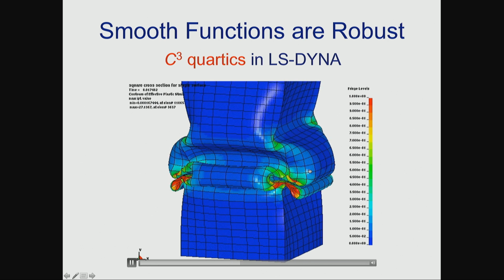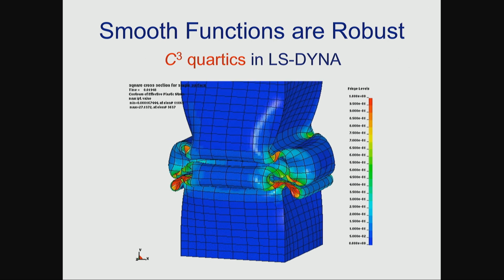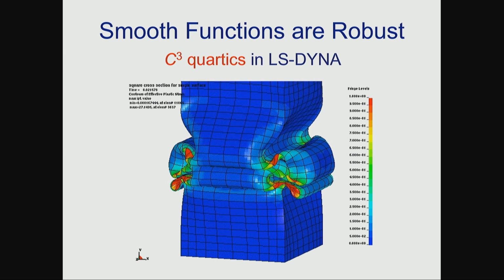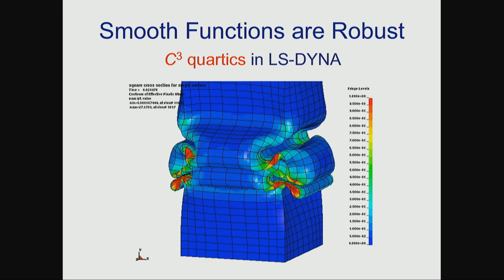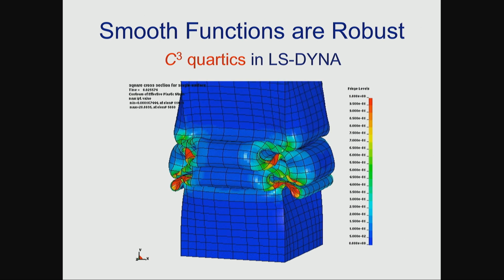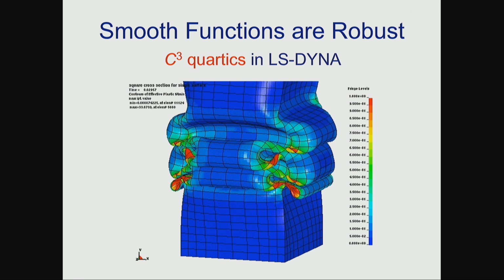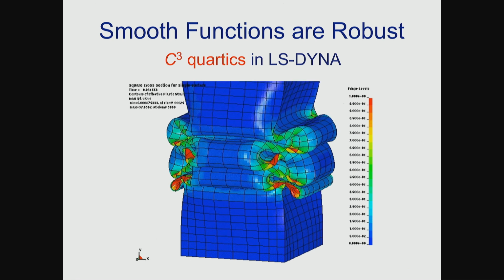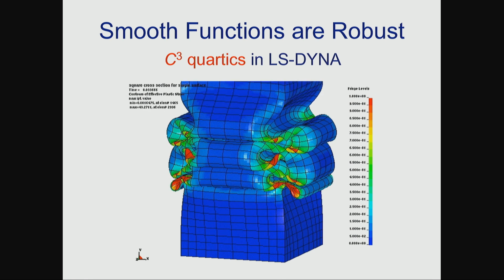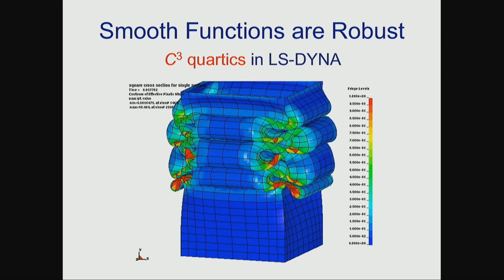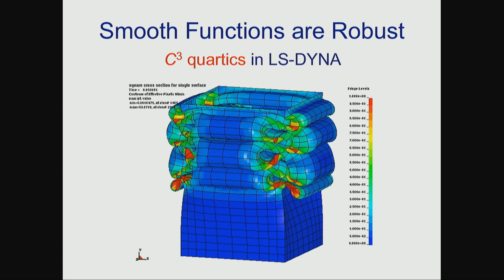The robustness actually increases with order here, unlike C0 finite element functions, which decrease with order typically. They are fragile. And that is one of the reasons they're not used in many of the hard problem classes that are exemplified by, say, crash dynamics, where you get many high-mode inputs.